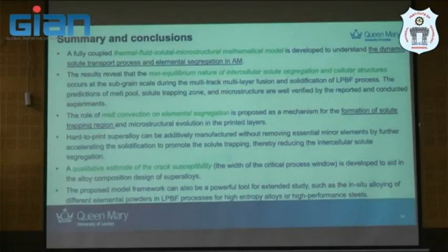So in summary, I just want to say that the fully coupled thermofluid solute microstructural mathematical model is developed to understand dynamic solute transport and element segregation in AM. We reviewed that the non-equilibrium nature of intercellular solute segregation and cellular structure occur at the sub-grain scale in the multi-track, multi-layer fusion and solidification of LPBF. The prediction of the melt-pool solute trapping zone microstructure are verified by the reported available experiments. So we have used both literature and also a new set of experiments.